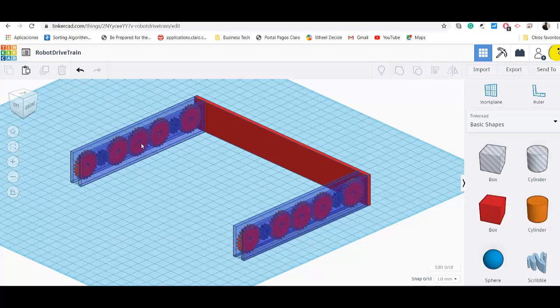in order to create a chassis, gears have to be odd. The number of gears has to be odd, so the rotation of the motor is the same on each wheel on the sides, okay? If you have an even number of gears, then the rotation will be opposite, okay? So, it's important that you have the odd number of gears.